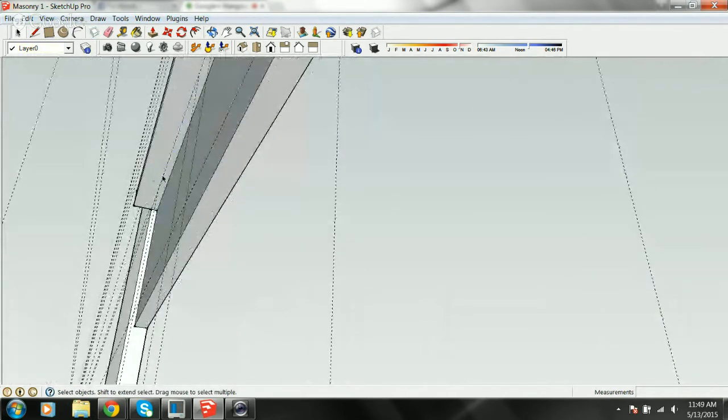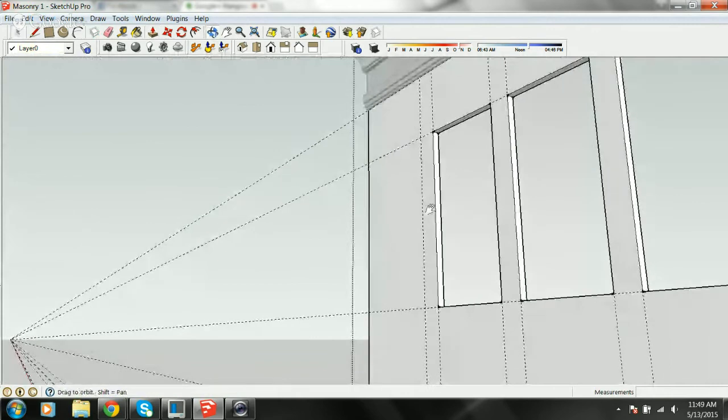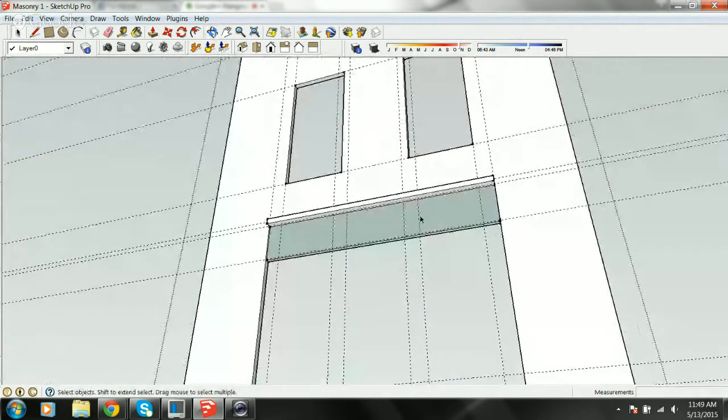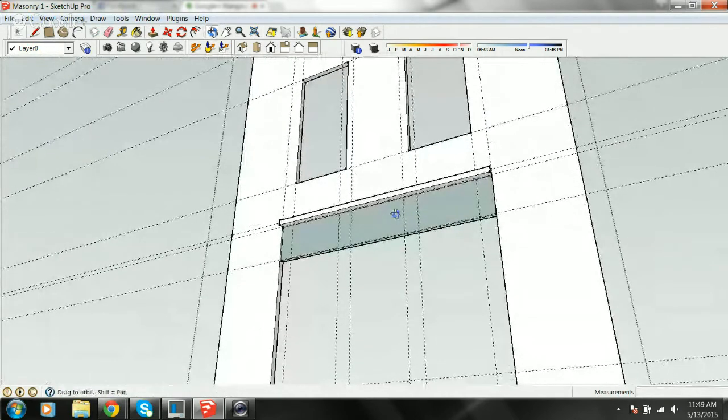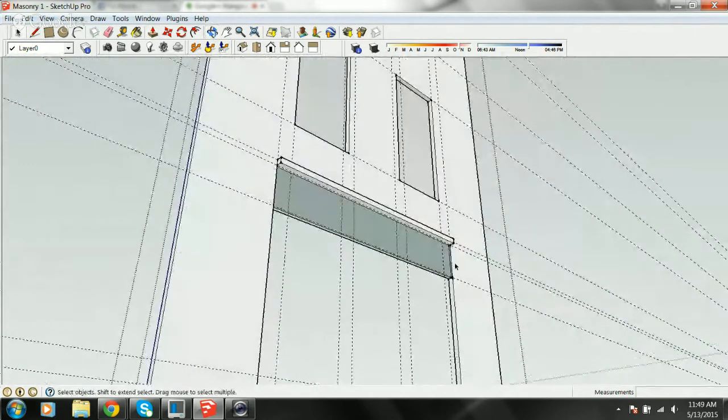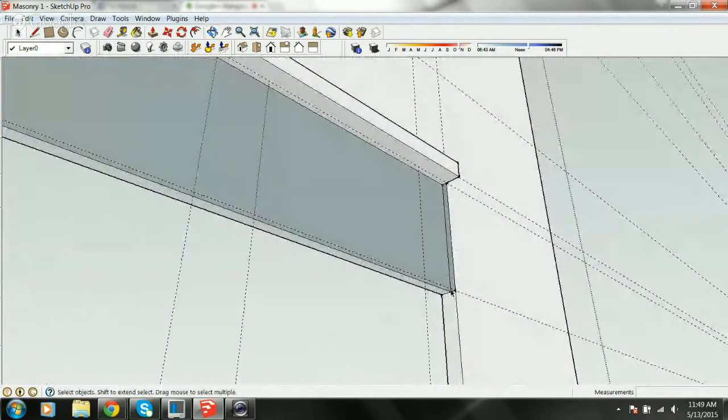I'm trying, like I said, to keep things clean. Yeah, housecleaning is important. Another tip: if you don't click on the model when you rotate and you click out here in paper space, sometimes the model will zoom out and go crazy on you.